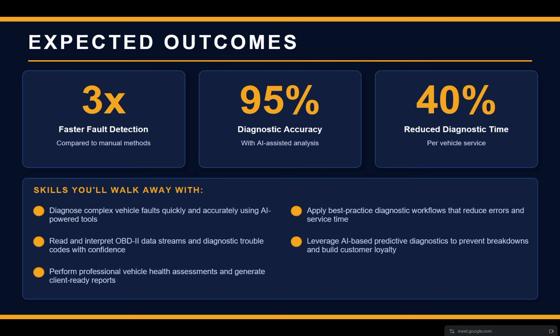You'll be able to read live data. A lot of us can read live data, but there are still many mechanics whose only use for their diagnostic scanner is reading fault codes. When they just see a misfire in this engine, or a crankshaft sensor code, the next thing is, go and change the sensor. So we have a lot of mechanics like that, but they are among us. In fact, most of us were at that place at one stage before we knew you can look at the live data to know where the fault is and how bad the sensor is. Maybe it's this sensor that is really causing this, or it's another thing, or we should check something else.